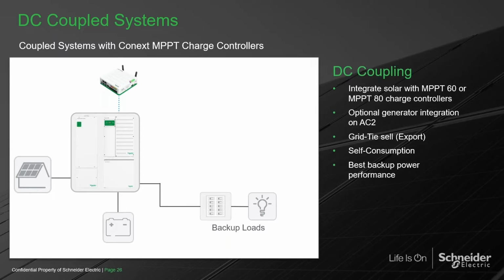So it handles up to 600 volts on the array, which means that you will have an array between 10 to 12 modules per string. Then this device, the solar charge controller, steps down the voltage to the batteries. So in a DC coupled system, the array connects to the system on the DC side. So here you have a very typical off-grid system. The array charges the batteries, and then the inverter manages to support the loads for the house.